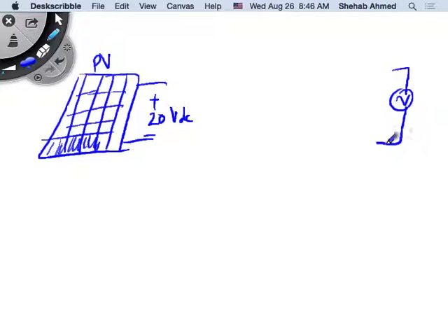But typically, let's say we're talking about 110 volts, 60 hertz. So how would I connect these? This is 110, this is 20. We said that the simple DC to DC converter topologies don't have the ability to step up voltage except maybe 4 times. So 20 times 4 is 80. So I cannot use a simple DC to DC converter, but I can use a more complicated step-up topology. I can use that, but how do I do this then?